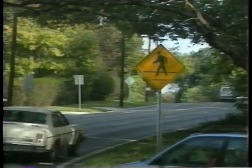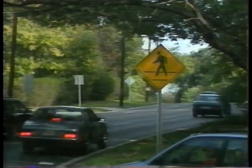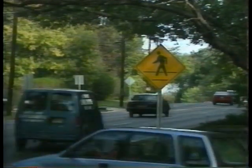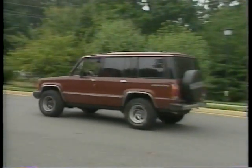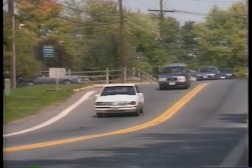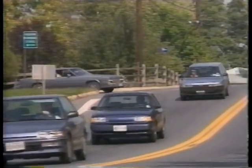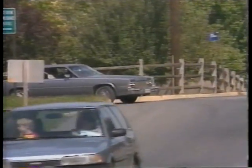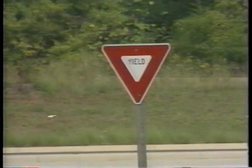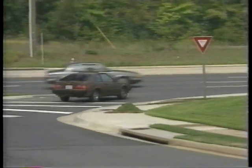A major street in an urban area is one that connects neighborhoods. Stop, yield, and speed limit sign placement is the same there as for local streets. Stop signs should be used when a side street enters a through highway or street. They are also used at an unsignalized intersection where a combination of high speed, restricted view, and accidents indicate a need. The yield sign is used at a minor flow street entrance to an urban intersection.